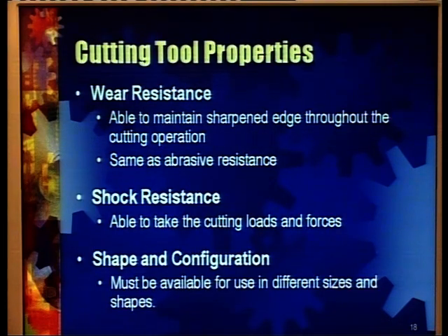And in case we require resharpening and replacement of the cutting tools quite often, then the proportion of setup time in the total machining time will be much greater than the actual machining time, and as a result the non-productive time will go much higher than the productive time in the total working cycle, which will seriously hamper the total productivity of the worker, the machine as well as the whole process.